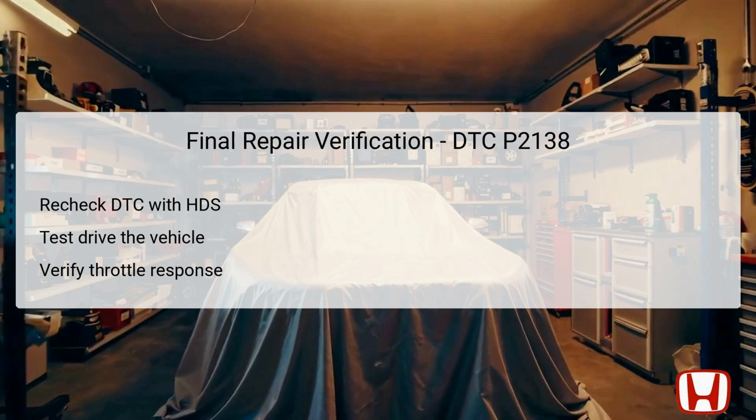After completing repairs for DTC P2138, it is essential to perform final verification to ensure that the issue has been successfully resolved. Start by rechecking for any DTCs using the HDS, ensuring that P2138 does not reappear. After clearing any new DTCs, a test drive of the vehicle is crucial to assess real-world performance and verify that the throttle response operates correctly.